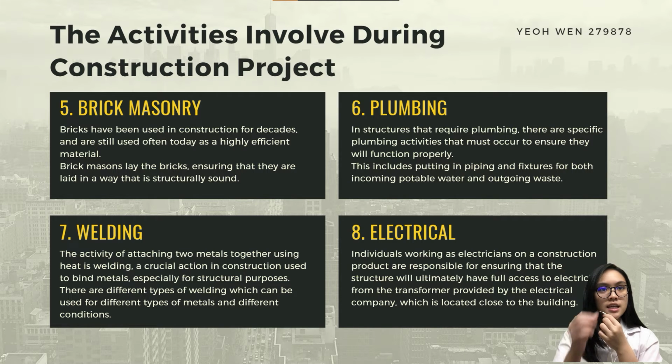The fifth activity is brickmasonry. Bricks have been used in construction for decades and are still used often today as a highly efficient material. Brick masons lay the bricks, ensuring that they are laid in a way that is structurally sound. For example, laying each brick directly on top of another allows cracks to go along the entire wall. If the bricks are offset, as you will see often, it makes cracking of the mortar less likely.